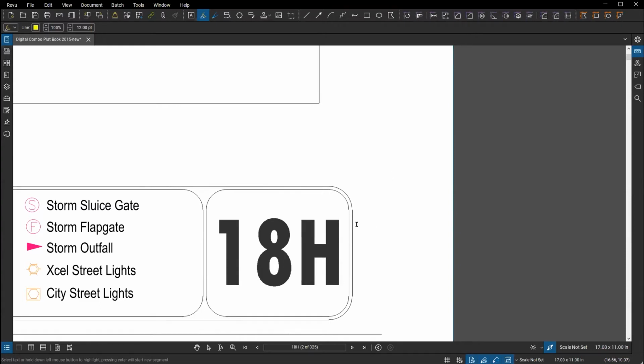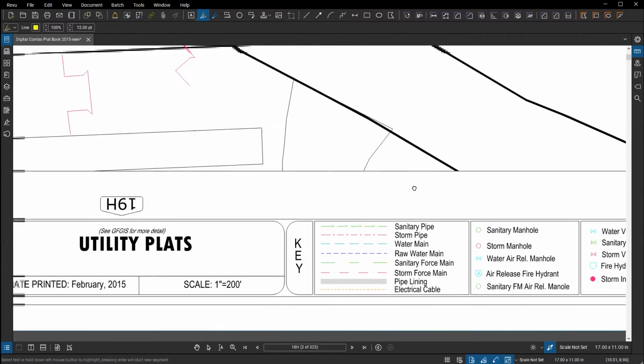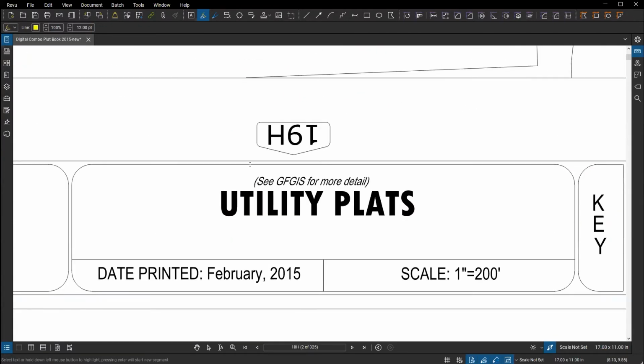So if you have text, it does this. Now that can sometimes be a potentially frustrating thing. So I'm trying to highlight, maybe it's a certain line I want to highlight, and I just can't do it because there's text there. So if I'm trying to highlight this line here, I can't do that because it sees the nearby text, which is now interrupting my option to highlight just the line the way that I want it to. I can turn off the option to query for the text by simply holding down Control.